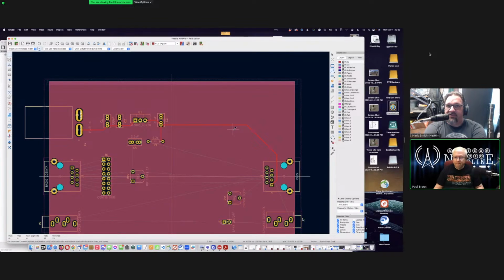Because any current that is drawn by the load, if you dragged that from R1, that current would pass through the trace between R1 and C3. And if there was any impedance in that trace between R1 and C3, that's an awfully short trace, so it doesn't really matter in this case, but in the larger grand scheme of things, whatever impedance in there would cause noise.